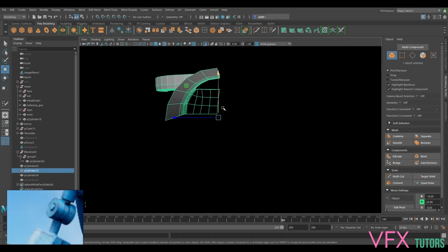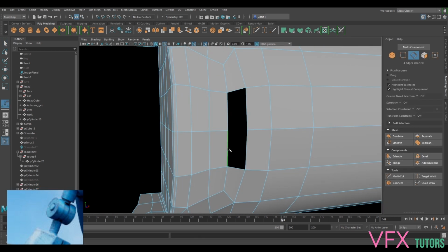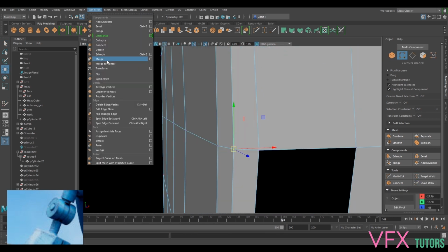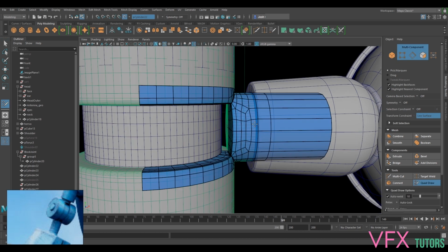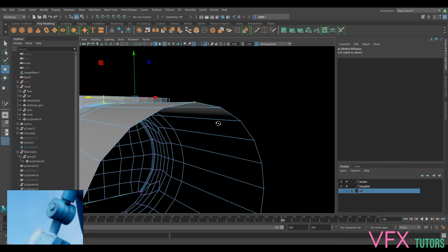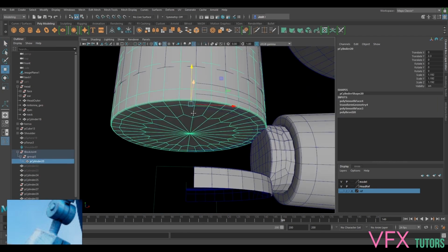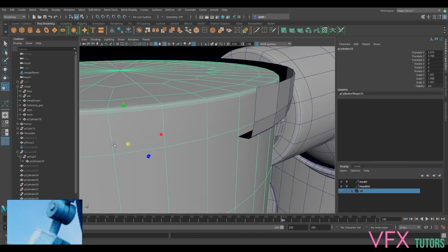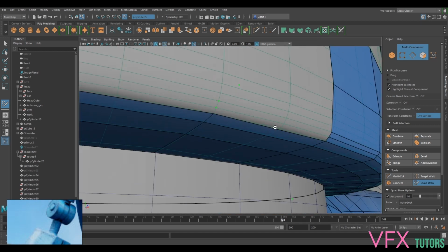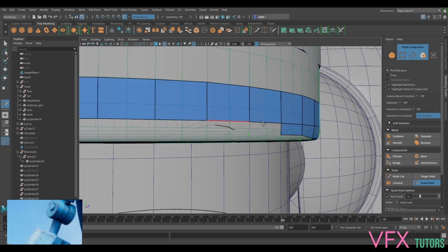So I'm basically, you can see here, practically rebuilding a section, because I can just delete 3/4 of it, then duplicate it across. So time spent just making that small amount of geometry, chopping a bit up, attaching it, it's figuring out where your time is better spent. Because you see here, I only make 1/4 of it, then I just duplicate it. Although I forgot to actually model up to 1/4, I think, so I had to add some extra ones in.